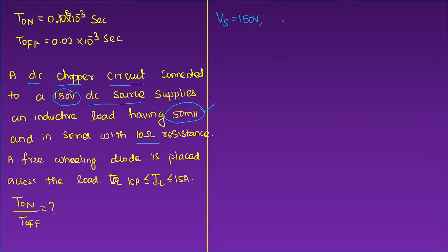You all know the purpose of connecting the inductor and capacitor in a chopper circuit. I had given the answer already in rectifier circuits itself. The inductor helps us produce continuous current at the output side, in order to get ripple free current, or continuous or constant current.